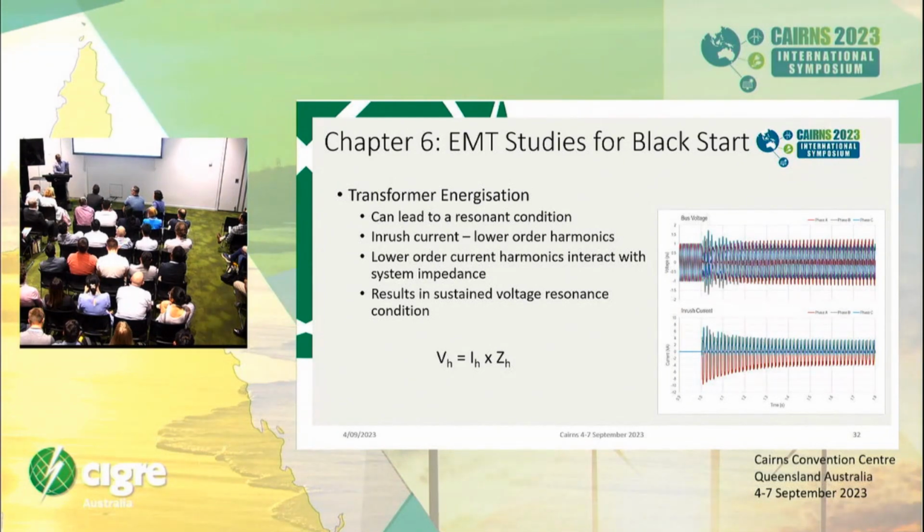I think Babak also has some comments on that point. That's a possibility. The voltage spikes, you have to be careful on that, between the simulation and real life. There is a possibility that some inverters may see a voltage spike as an undesirable condition and immediately trip.